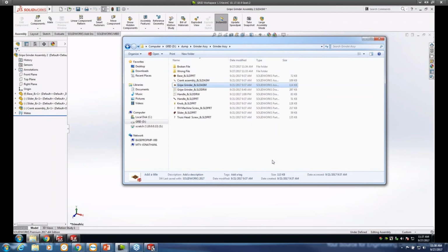If you do follow the SOLIDWORKS search routines, SOLIDWORKS might be able to open up the correct file, and you can save it, and then everything will still work fine. But there's always a risk that you can break those references when moving them around in Windows Explorer here.